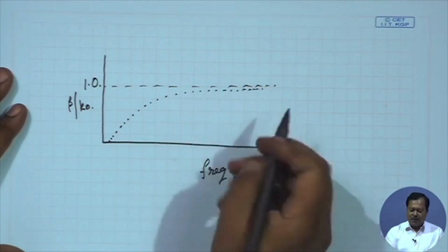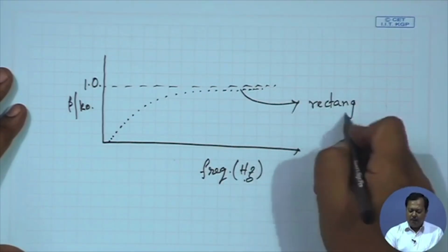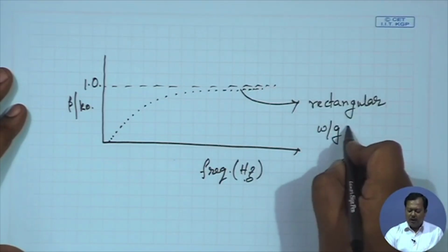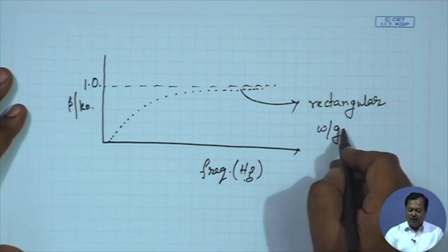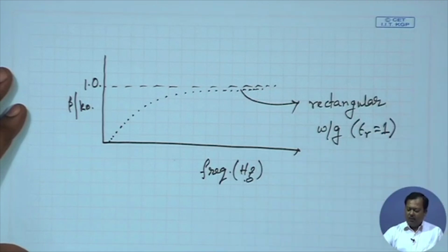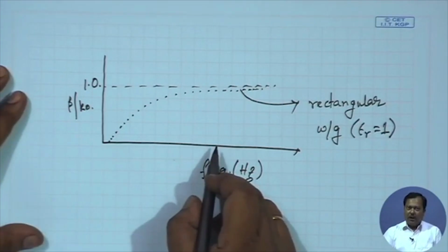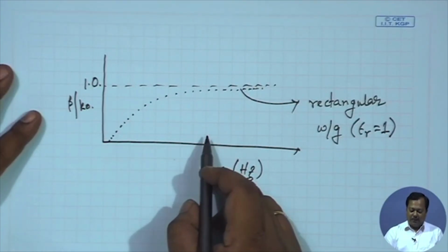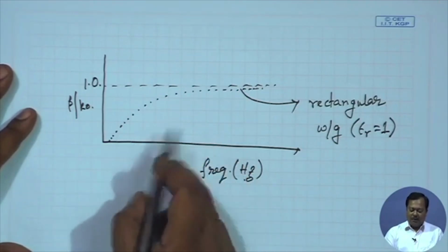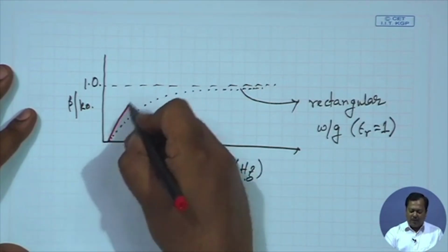It will always be a fast wave. This is for a rectangular waveguide, air filled without any dielectric, where epsilon r is equal to 1. Now, for the SIW structure, we always have some dielectric material present. So we are loading it by epsilon r, and now let us say we have adjusted the width so that they have similar cutoff frequencies.